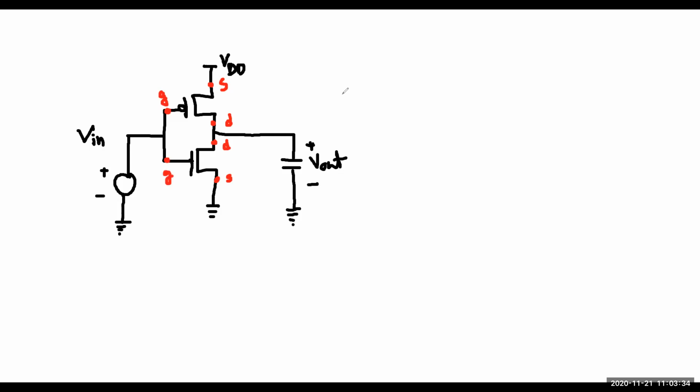Now, if we take a multimeter and take a reading from here and from here, what are we measuring? We are measuring VGS, the gate to source voltage. Can you see it is gate to source voltage? So let's write VGS in NMOS, that's why I'm writing VGSN.